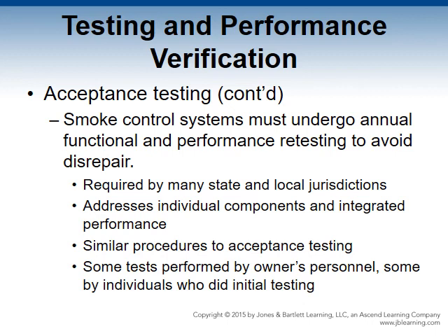Problems may be a result of multiple factors: reprogramming of the fire alarm system, electrical disconnects due to nuisance operation, damper motors failing to operate, disconnected damper linkage, or fan motors tripped on thermal overload. Verification of these control sequences and responses occurs during the final acceptance phase of construction, and then the owner is responsible for that annual testing throughout the life of the building.